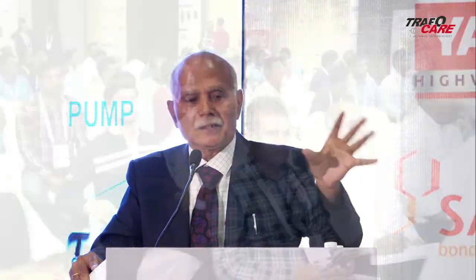So, degree of polymerization can be measured by taking the paper out. Earlier, prior to 2000, we used to take out the paper and analyze its mechanical strength and its degree of polymerization. But this becomes an intrusive technique; we are going to disturb some of the insulation. So, this is also being done to have a comparative check whenever the situation is too worse.